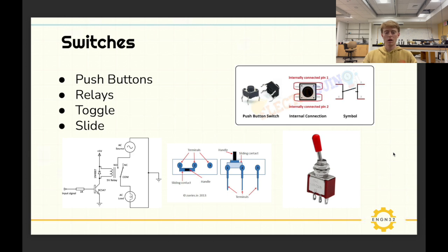All right, relays. A relay is this picture right here in the bottom corner. I see relays used a lot in higher power systems. For example, if you've ever driven a golf cart, when you press on the pedal, you hear a click. That clicking sound is the relay contact slamming together. So how does a relay work? I basically have 2 contacts and I want one of them to slam into the next, and that completes the circuit. So it's a switch and it's powered electrically.